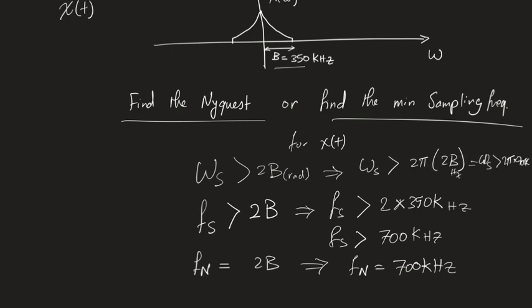Okay? So if you use omega or W, the radian frequency, make sure either that the graph there is showing things in radians or you convert to radians. Don't forget that. Or the other option is, since the values on the graph or in the text were given in hertz, just use Fs and Fn instead of Ws and Wn. This is a simple question.